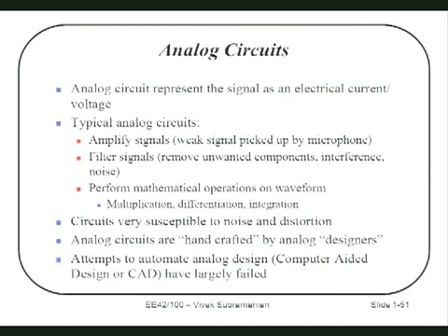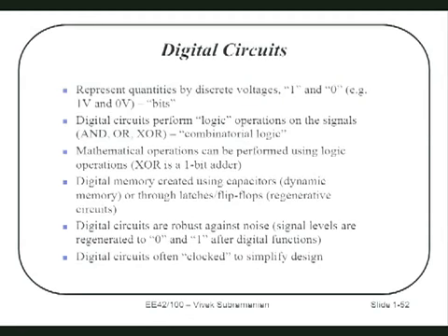Digital, on the other hand, separates the world into discrete levels. We talked about these in the last class. We can have discrete voltages, for example, 5 volts and 0 volts, which we might call 1 or 0. We call those bits. Anybody know where the word bit came from? Why do we call it a bit? Yes, binary digit. Take the B and the IT, and that's bit.